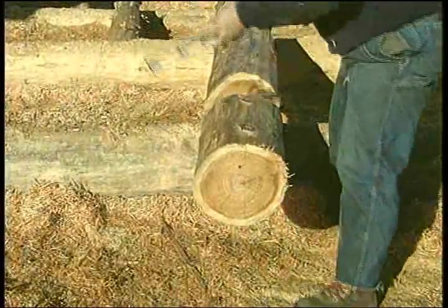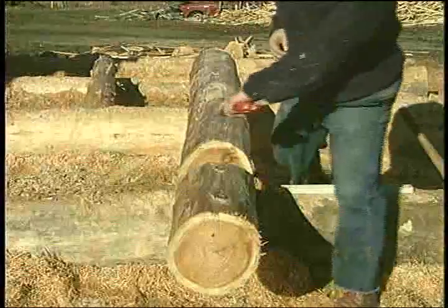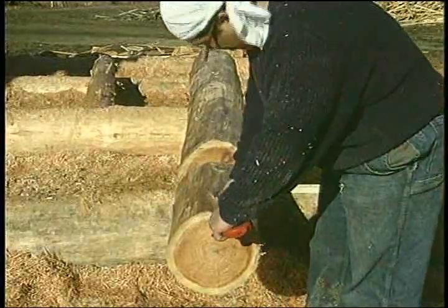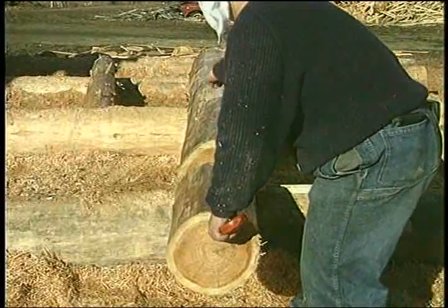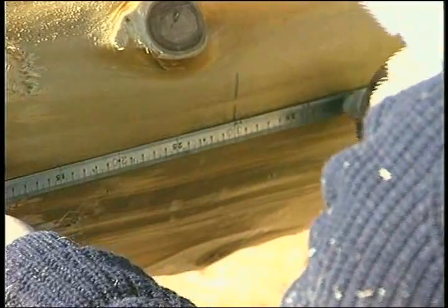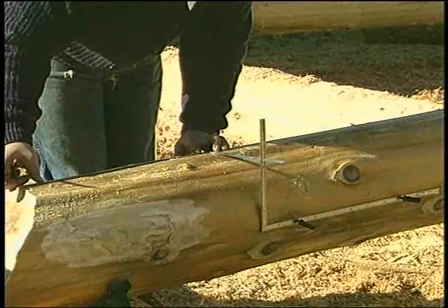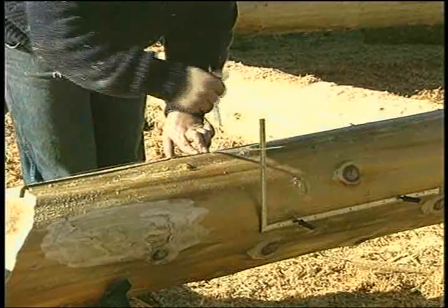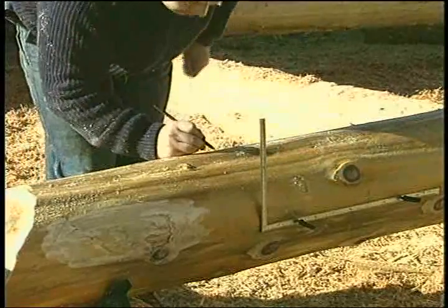Before you cut out the groove and the top of the window opening, snap a center line onto the bottom of the log and use this to bring the cut lines across at right angles. The cut line can be located in a very standard and accurate way by using two squares on the center lines. Bring the original end mark up to locate this length on the center line. Use the same system to locate the mark on the inside level line.